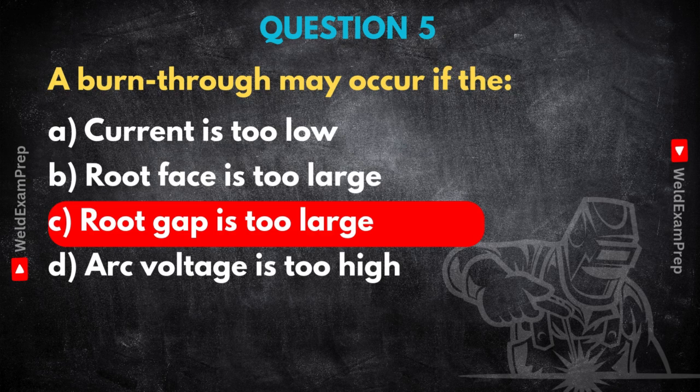Yeah. Understanding the why behind defects like burn-through or incomplete fusion, or knowing why leg length is measured. That critical thinking is what transforms someone from just looking at welds to truly inspecting them effectively. Couldn't agree more. It's about anticipating issues, diagnosing them correctly, ensuring quality right from the start.